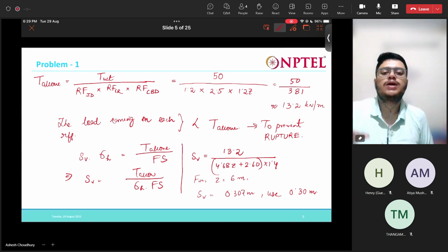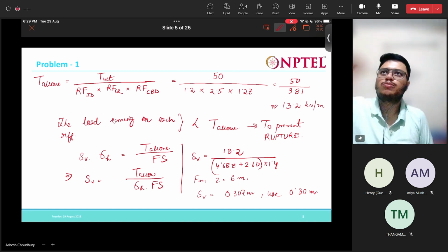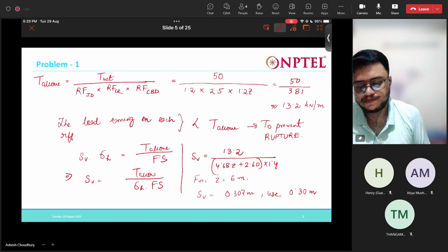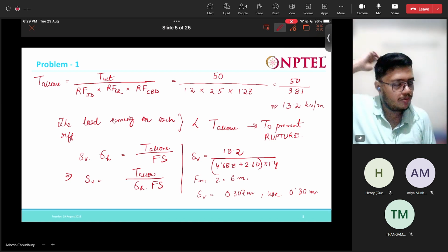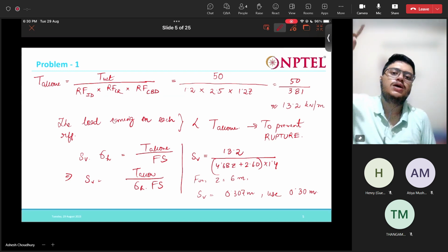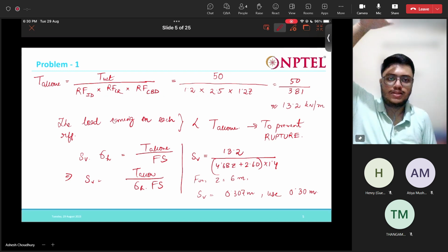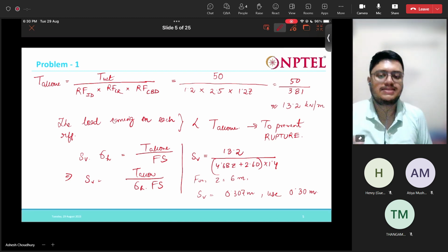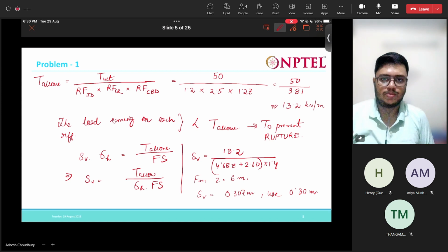Okay, now what we can do, as the height increases, if you see, at z, z reduces. We are measuring z from the top, right? So as z reduces, means as we are going up in the wall, we can relax this spacing, so that our design becomes more economical.